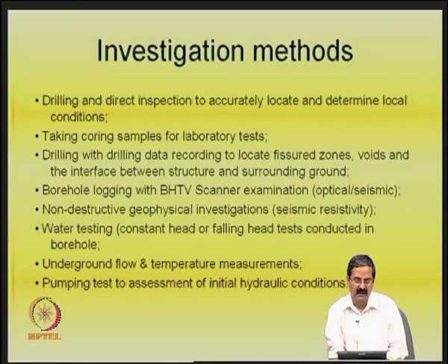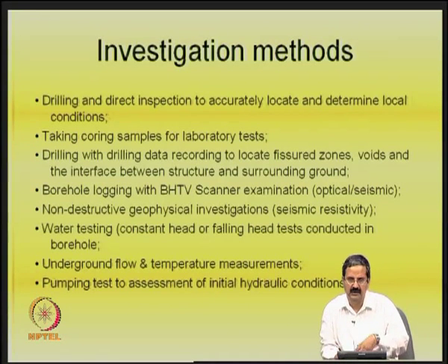Then you should be able to understand the underground flow, how it moves. Say for example, in a particular area, the underground movement of water could be in some localized conditions. One should be able to understand that only that area needs to be stabilized. So, many things, say for example, the velocity of the flow underground also influences your choice of the grout, because the grout material should not get washed away when you are trying to do the grouting.